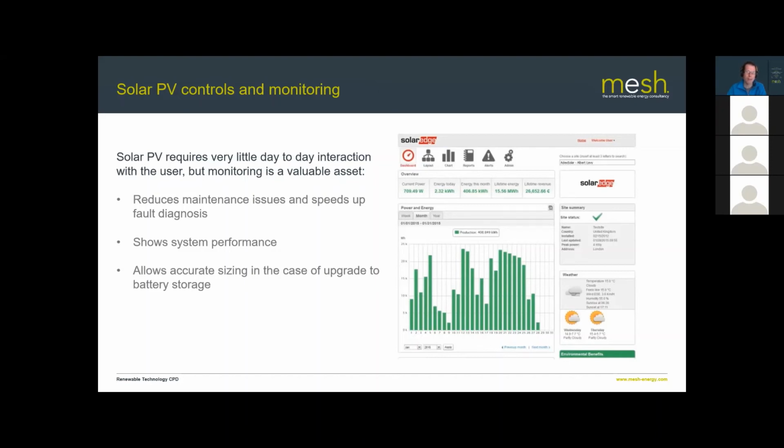And that's not just how much do I use in total, it's what times a day do I use it, what's my peak demand, what's my minimum demand, do I use my electricity in the evening, in the morning, do I have a spike between 7 and 8 a.m. when I'm making breakfast, do I have another spike between 7 and 9 p.m. when I'm cooking my dinner and watching TV, how much usage do I have at midday? All those things will affect what the ideal size of the battery is.